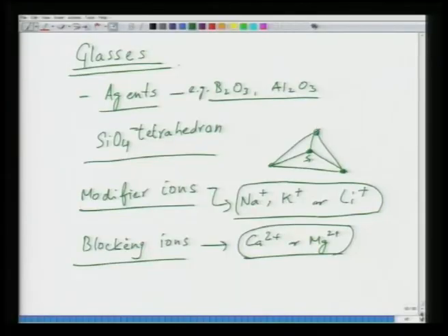In these cases, now the important thing about glasses is that they are commercially important. Commercially important means they have to be made by furnaces. Now, they have to be melted by the furnaces, and typically they are melted in electrical furnaces. And now, when you melt them in electrical furnaces, then resistive heating of the glass is the mechanism which is used to melt them, which means the resistivity is an important factor. They cannot be too insulating. If they are too insulating, you cannot use them for heating purposes. You cannot melt them in a furnace using resistive heating.